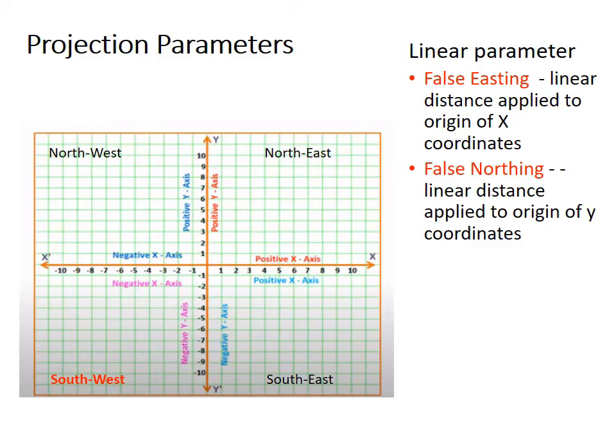A map projection is not enough to define a projected coordinate system. We need some more information like where is the center of projection, whether a scale factor is used or not. Knowing all this information exactly for the projection parameters, the Earth can be projected properly.